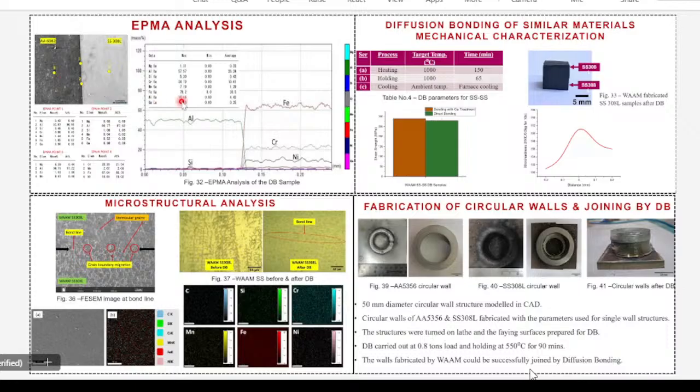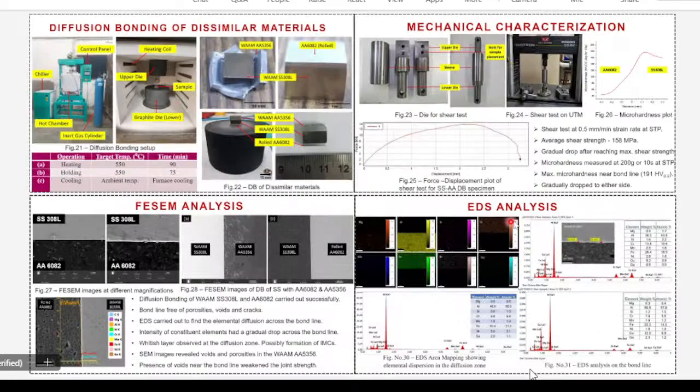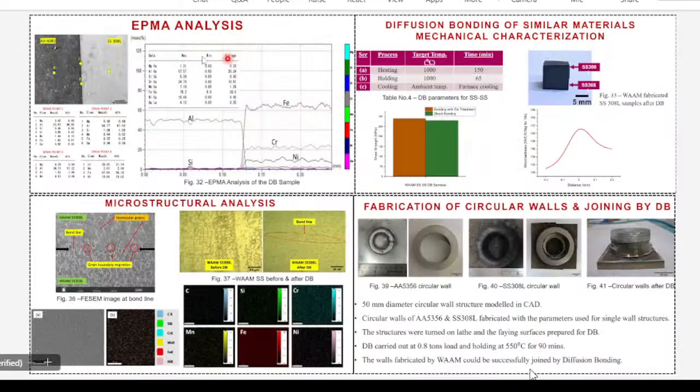So this gives the exact percentage, and EDS doesn't give exact results for atomic number less than 10. So for atomic number less than 10, we have to consider EPMA, because EPMA gives accurate results for atomic numbers less than 10. Suppose we have to quantify nitrogen percentage, we don't want inaccurate results. So EDS we can skip, EPMA we can do, and it will measure the exact percentage of nitrogen,